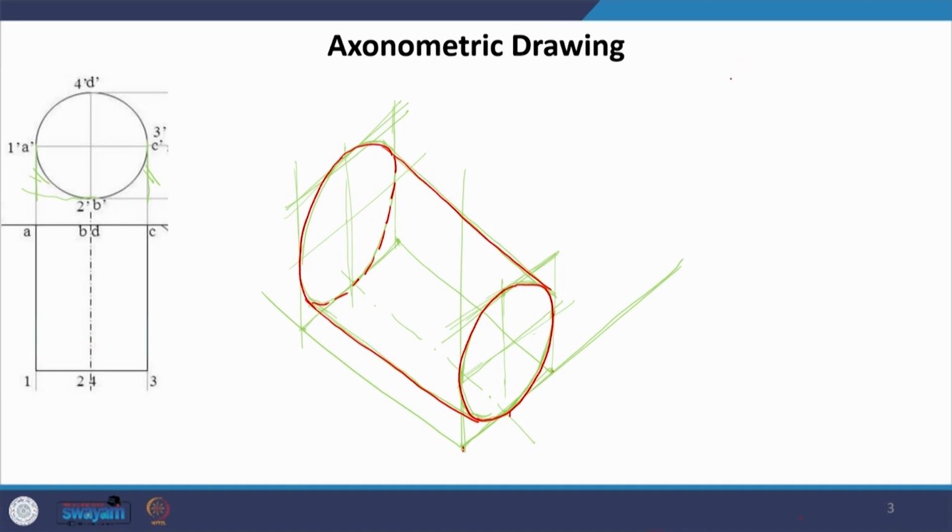Right now you might be thinking, why can't I start by drawing the elevations first? But we are going to be using axonometrics mostly for drawing the architectural views, where the architectural plans have already been drawn, and it is much easier to just rotate the plan by 45 degrees and raise the heights, whatever heights you have taken for different building components, and arrive at a 3D projection.